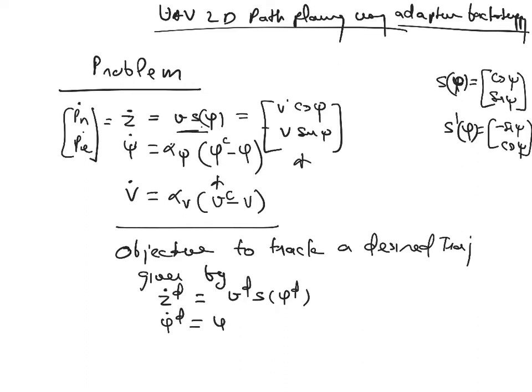So the desired trajectory can be controlled by u. Whatever you want, you can make a sinusoidal trajectory, you can make a circular trajectory. If u is 0, then it's a straight line, right? Because that's the turn rate. So you can control that, and v desired dot equals 0, so it's a constant. So the trajectory is a constant velocity trajectory. So what are you doing? You will have to solve this in an S-function to give you a desired trajectory, basically, right?